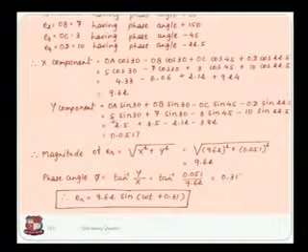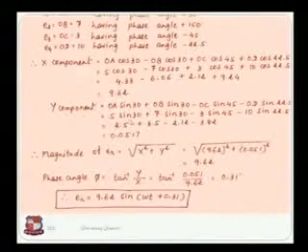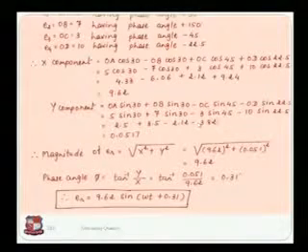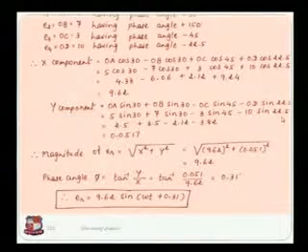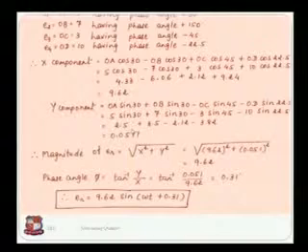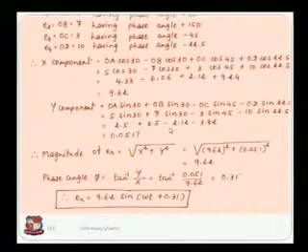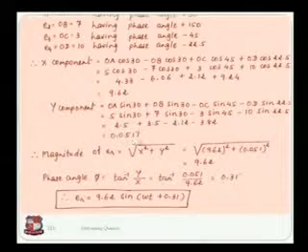So it is like this: 5 sin 30 plus 7 sin 30 minus 3 sin 45 minus 10 sin 22.5. So it is equal to 2.5 plus 3.5 minus 2.12 minus 3.82, and the answer is equal to 0.0517. This is your y component.